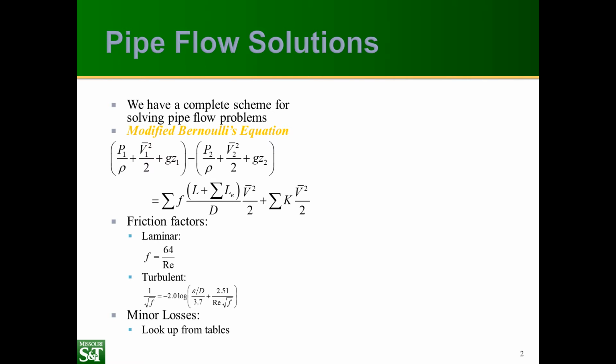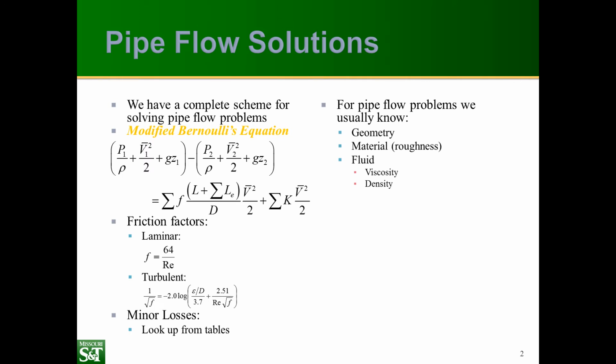Usually we know the basics. We know what the system looks like, the diameter and length and so on, and what it's made of. You know, the fluid, the material of the pipe, and so on. And then we usually have two different types of goals. The first class consists of either finding pressure drop or finding length, given all the other parameters.